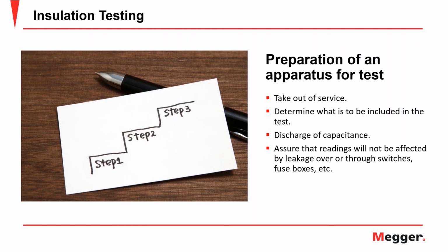So make sure that anyone doing an insulation test is made familiar with this and made aware to just watch the display and be careful of the discharge. Okay. And then, of course, we do mention that you could have noise from surrounding circuitry.